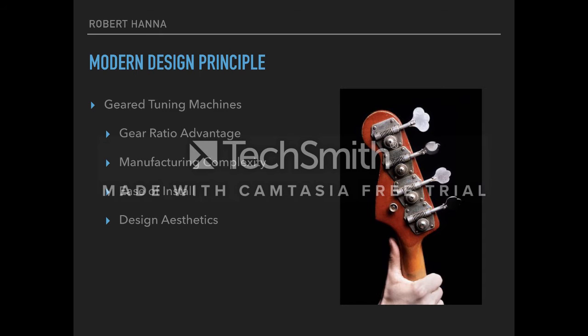So more recently, as far back as past 100 years, a couple hundred years, we started using geared tuners. So instead of just relying on friction here, we add a little complex machine of a tuning peg in line with a worm gear, which turns a pinion, which is attached to the capstan, or the little post that the string is fed through and wraps around. So the capstan attaches to the pinion, which attaches to the worm gear, which is driven by the knob. So what this does is it gives us the advantage of having gear ratios dictate how much of the knob turn translates to a capstan turn.